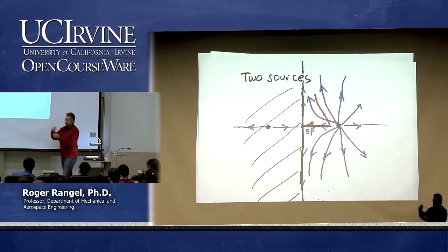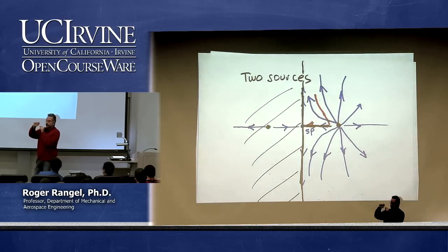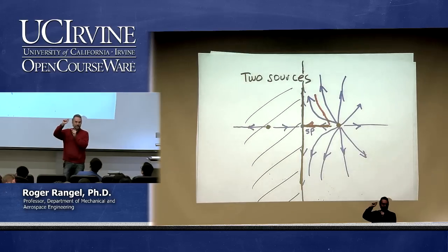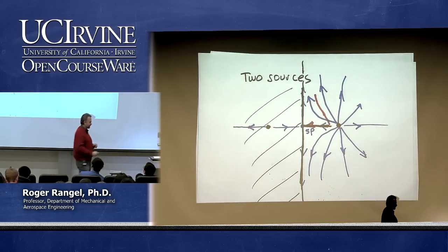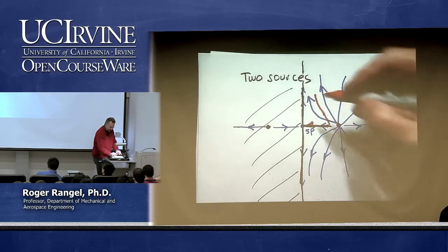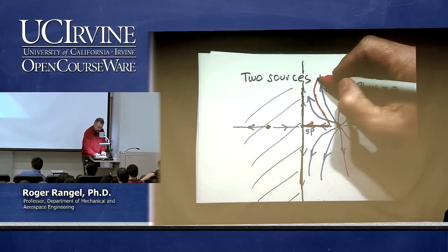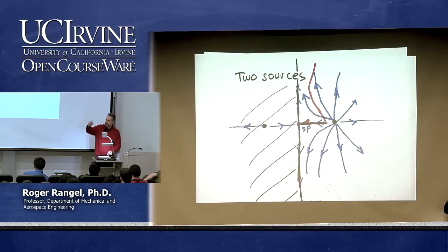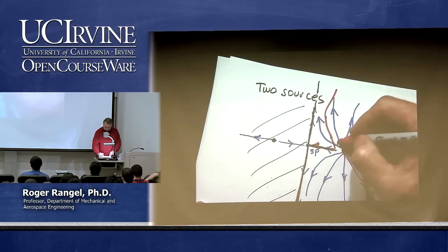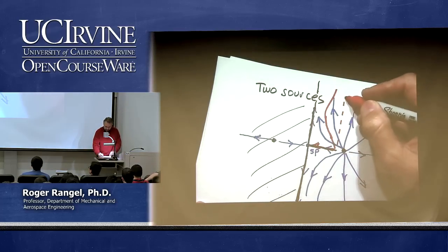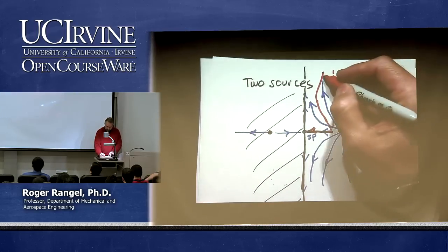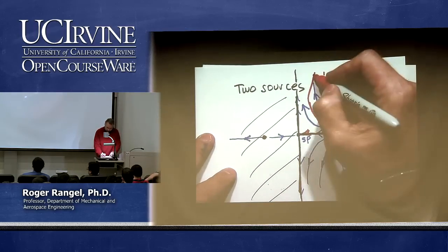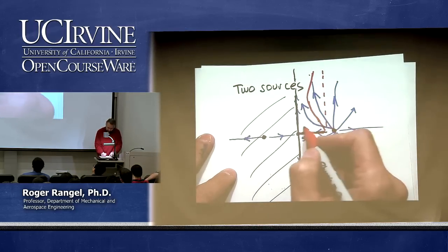Right? It will be less because the fluid is speeding up. But then the fluid at some point is going to probably reach a maximum velocity and start decreasing again. So it looks like this pressure will have to build up again as I go far away. But of course, if this is the stagnation value, it will approach that, it will go in that direction, but without actually reaching it.